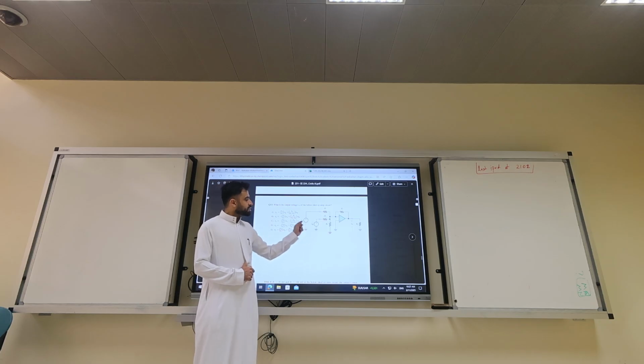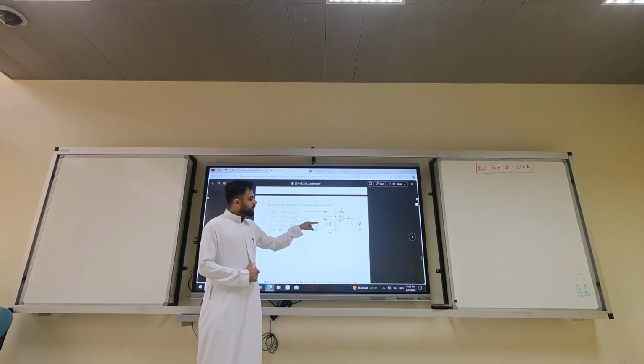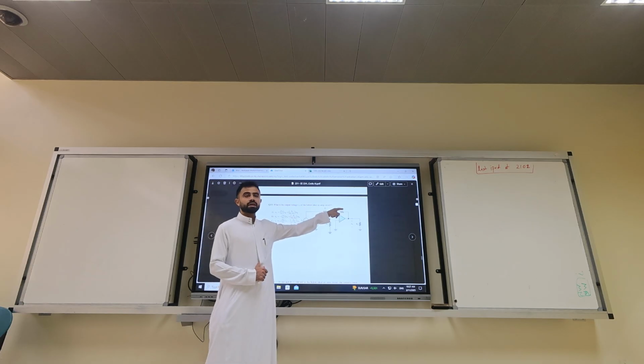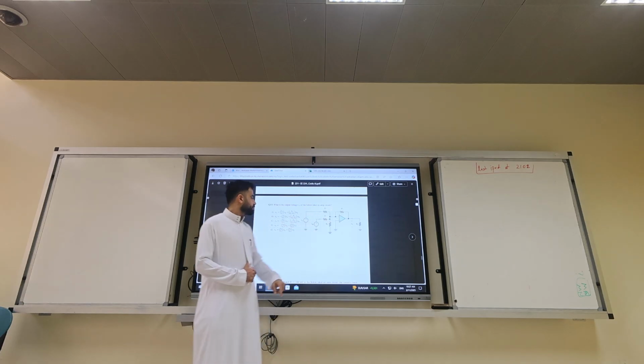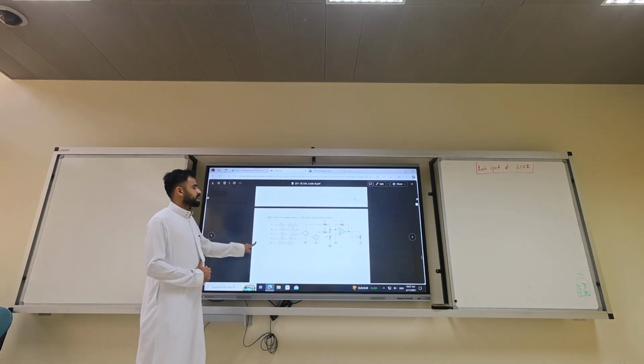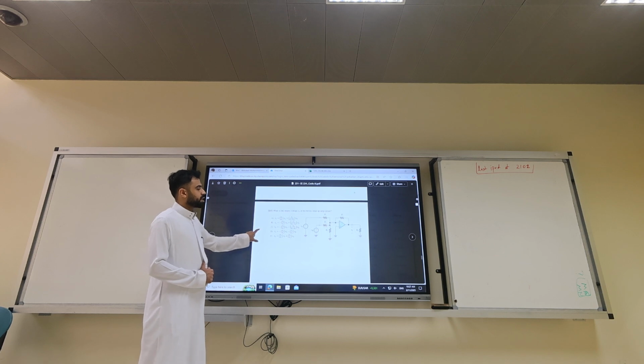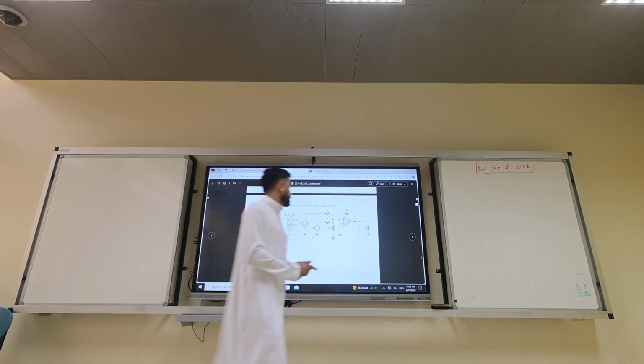In a classical inverting amplifier, this looks like a summing problem, right? But this summer is not classically connected. There are 2 resistors here. Because of that, you have to find R4 parallel with R2, and the equivalent one is an inverting amplifier with R3. So I don't know what the answer is. Can you guys calculate it? Should we try to do it? Maybe.